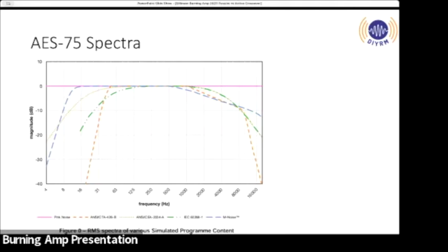The dynamic range is higher up there. And when you listen to that noise, it kind of sounds like pink noise with extra popcorn in it, right? Extra pop, pop, pop sounds because the dynamic range has to be high, but the continuous long-term power is actually quite low. I don't remember, it says it in their paper. It's actually 10 dB over 5 octaves.